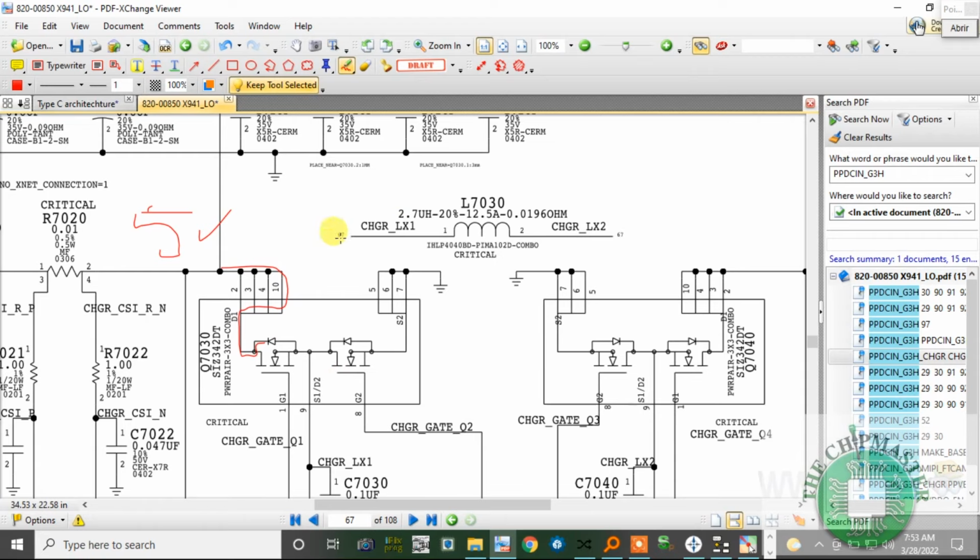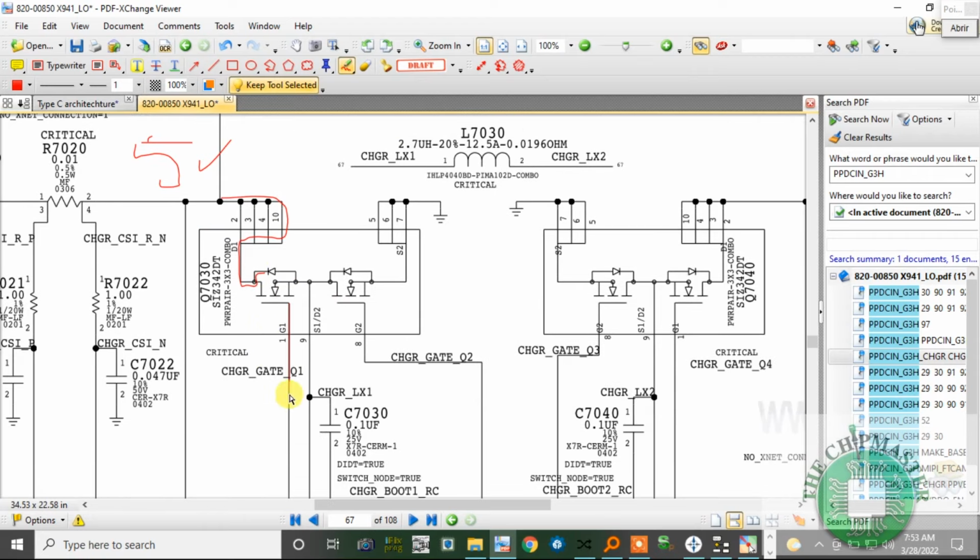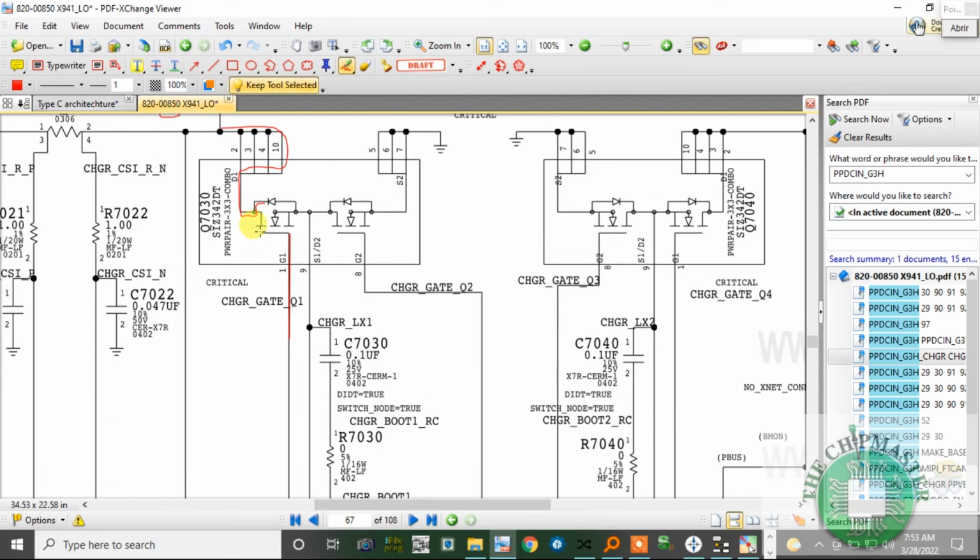So it needs to be cut. So this MOSFET, right, the G1 pin needs to be conducted, and this is an N-channel MOSFET, as you can see, right? So this voltage needs to be higher than the voltage at its source. So its source is 0 volts at the time. So with 4.5 volts or more, which is the threshold, 4.5 volts or more coming to this gate, then it will do a full conduction, right?